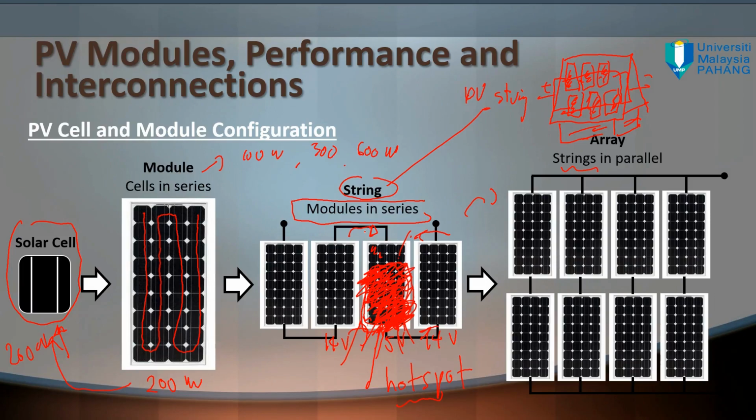Recently I heard from several students who work in solar companies, I get some input from them, that they are now using drones, not sensors. They launch the drone, which is equipped with a thermographic camera and image processing, so they can see the thermal difference.